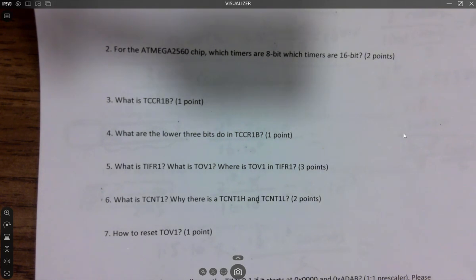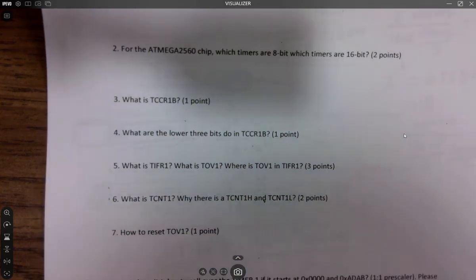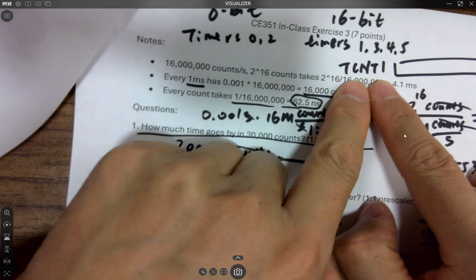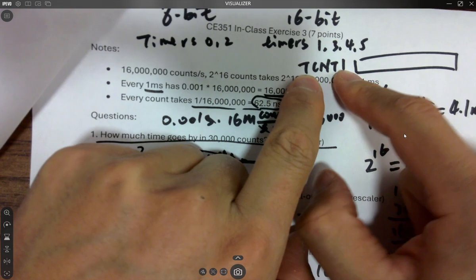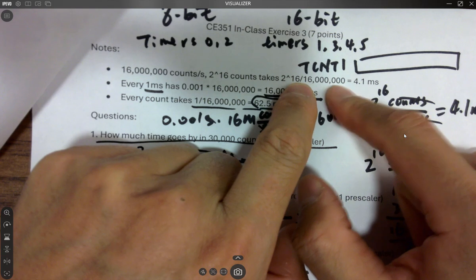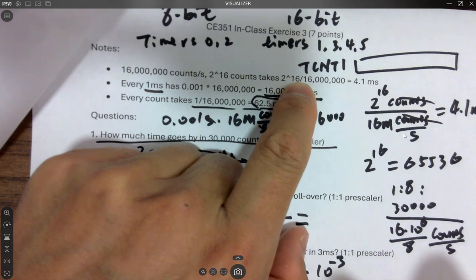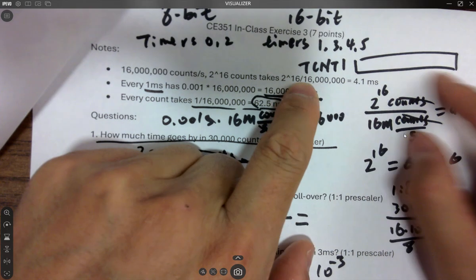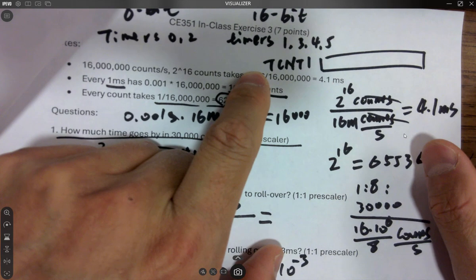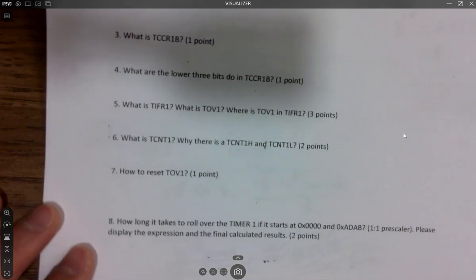But also it has 2. It's TCNT. This is actually TCNT high 1 and TCNT low 1. It's actually 2 8-bit registers. It's not really a 16-bit memory bank. It's actually 2 8-bit registers, so all of them are organized in 8-bit format.